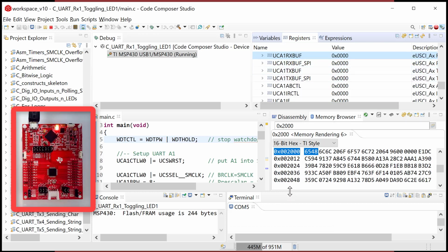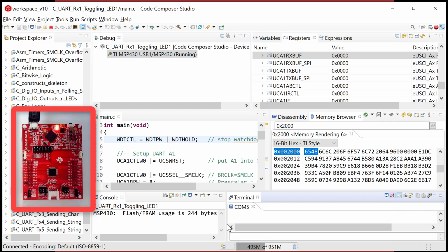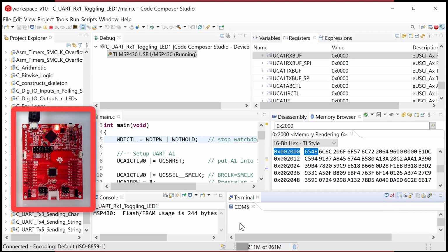Now since we're only sending one character, there won't be too much contention between the debugger and the UART. So we're just going to send one character. Before you send anything, this is a really important step: toggle back into the mode where you just hit one keystroke and it'll automatically send without echoing it. So let me show you. Don't get in the mode where you have to hit return, and I'll show you why in a second. Go back into this right here.